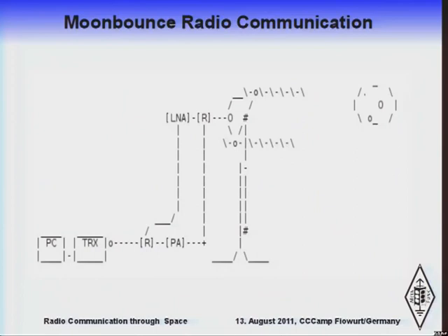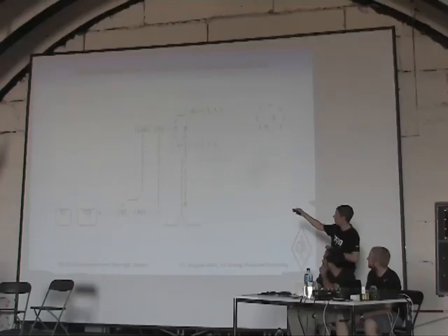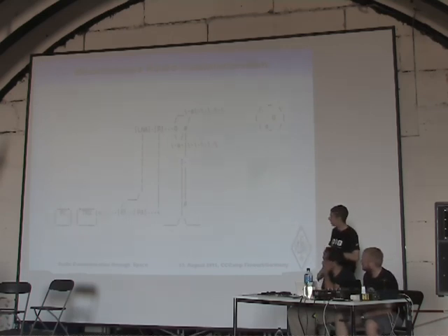We've got the mast here, the 2 antennas. They are combined over a power combiner, and here's the coaxial relay, whereas the low noise amplifier is directly connected to a coaxial relay, and then we are going with the thick cable to the power amplifier and a small transmit or receive coaxial relay that's just switching the receive and transmit path.